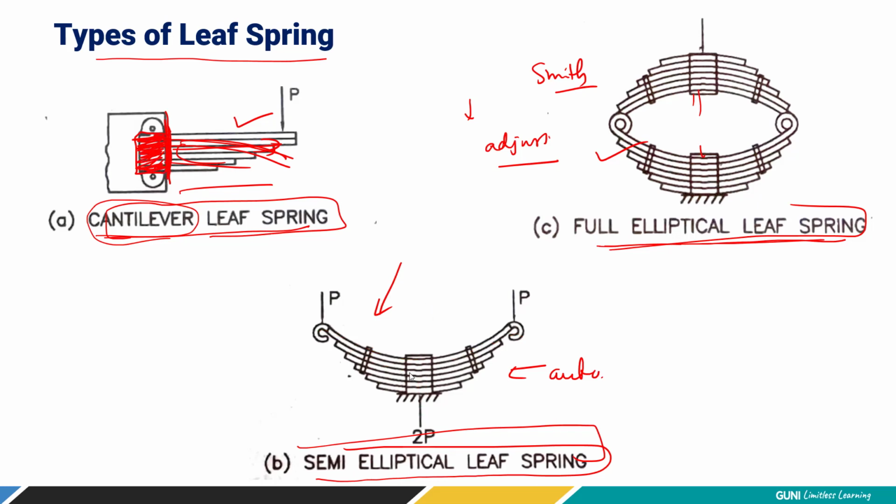So here in the semi-elliptical spring, whenever you use the U-bolt, it is going to make this length of all the leaves a solid one, right? It is not going to deflect. So we have to subtract that. We cannot consider that length in deflections.